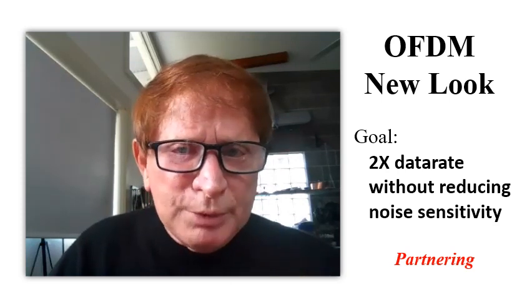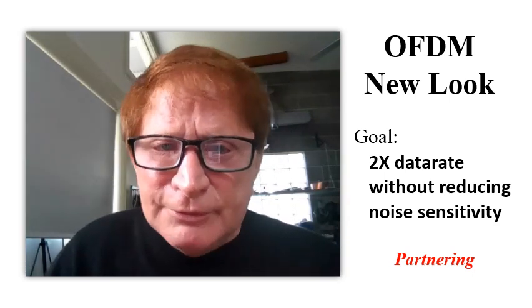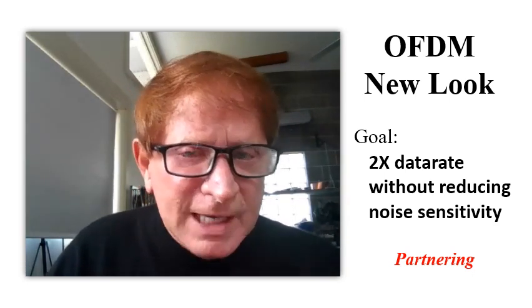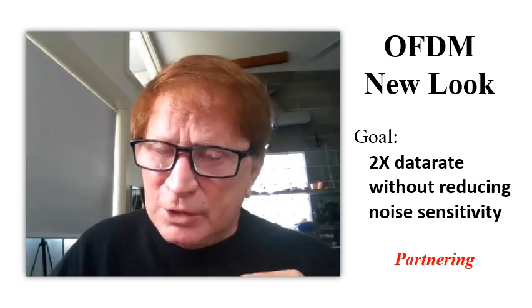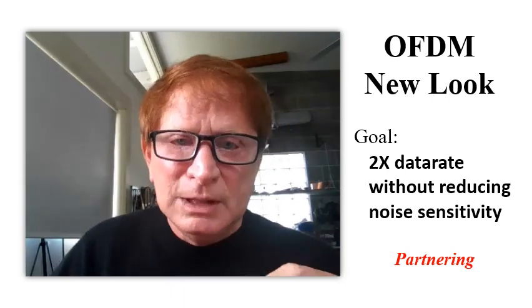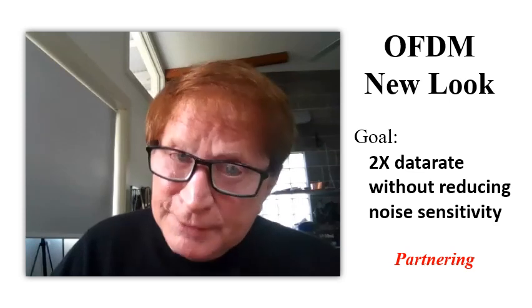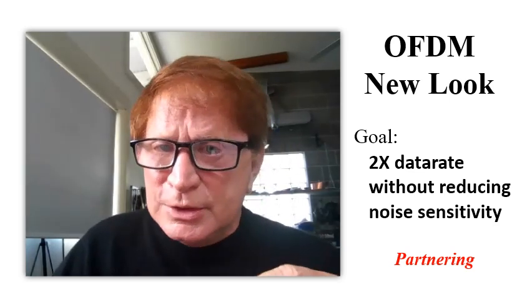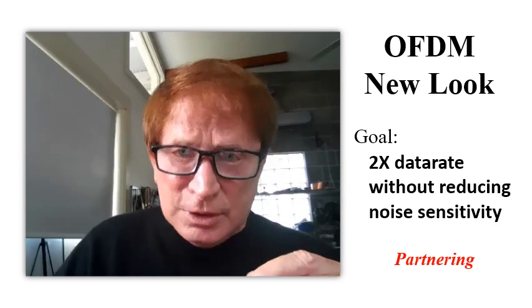The key to our new approach will be replacing the FFT at the receiver to achieve faster symbol demodulation without sacrificing the graceful degradation of the current OFDM implementations. We will also rethink the cyclical prefix, the channel equalization methods, and the receiver frequency synchronization.